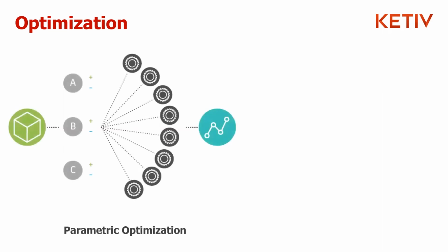Now, optimization in Moldflow takes two forms, right? The first one is called parametric optimization, and that focuses almost exclusively on geometric variables. It's essentially an automated way to adjust all your different variables and run a series of analyses without actually changing the original CAD model.